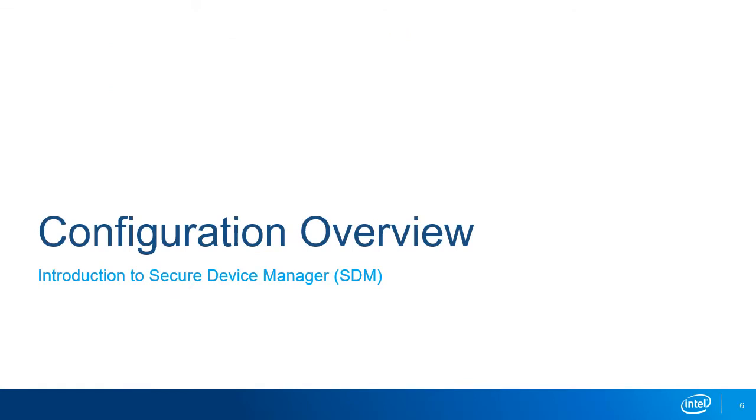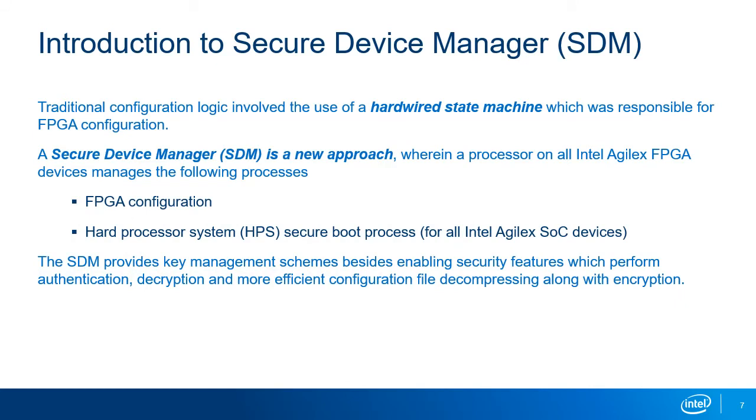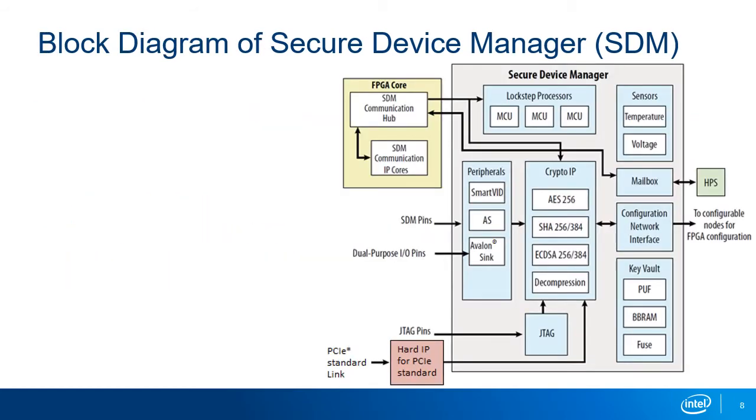The next part of this section introduces you to the Secure Device Manager. Until the introduction of Stratix 10 FPGAs, configuration logic has been hardwired into state machines. Stratix 10 and Agilex FPGAs changed that approach by dedicating a Secure Device Manager block for FPGA configuration and secure boot process. This slide covers the Secure Device Manager, or SDM, capabilities.